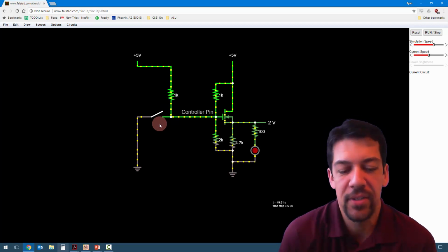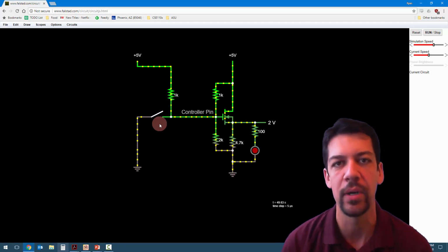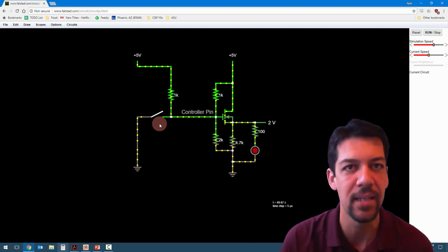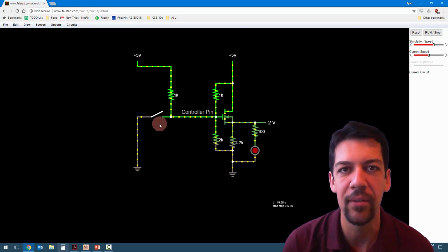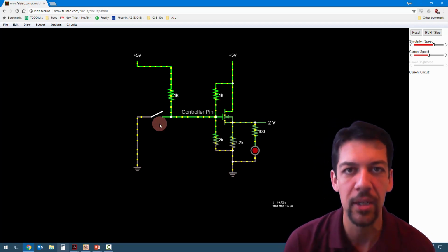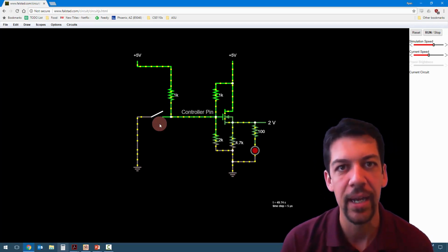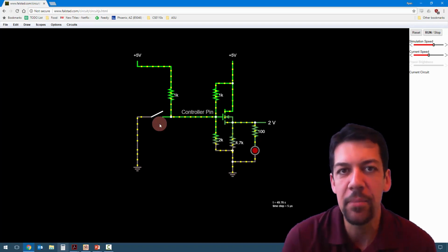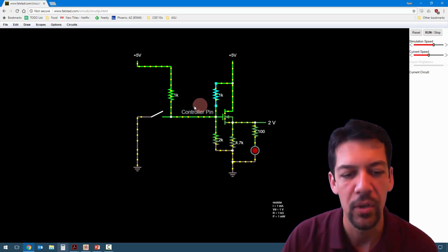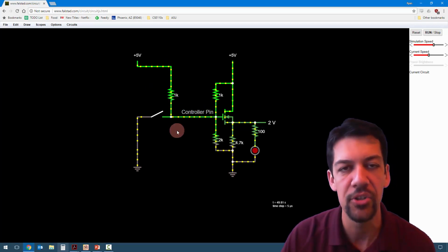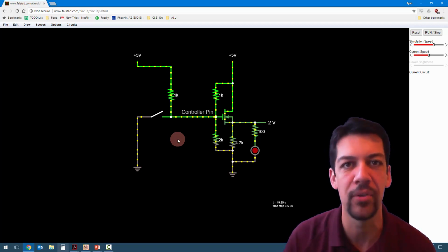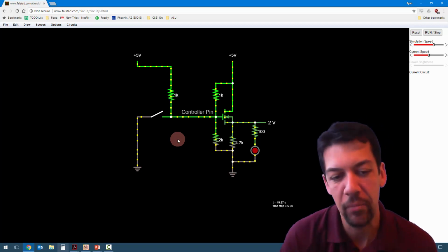And you might find there's strengths and weaknesses to either one of these configurations, whether basically we're looking for the lowest power consumption. So depending if it's a circuit that's normally open or if it's normally closed, you might want to use an active low or active high configuration, mainly because you want to minimize the amount of current that flows through this resistor. So this resistor should be placed in whatever configuration minimizes the amount of current that's flowing through it at any given moment, right?